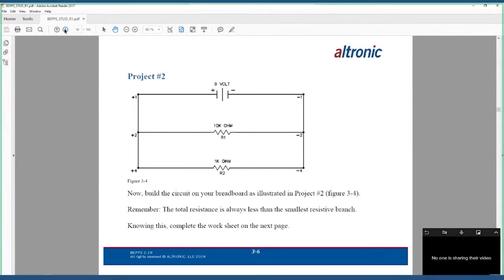So let's see. This is where, how many of us have ever been, let's try to put this in a practical sense, measuring resistance on a circuit and sitting out there scratching our heads, not understanding why we're getting such an obtuse number? An example is, I have a fuel valve coil, but I know if I take it out and put it on the tailgate of my pickup truck or in the front seat and measure the resistance by itself, it might be 4 ohms.